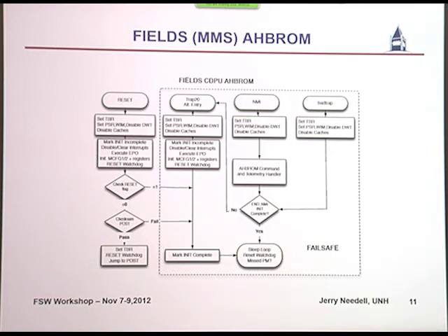In this case, the only telemetry required and the only telemetry produced by this is either response to a command, and that response to a command, as you'll see later, is only going to be a read of a memory location, and then also a heartbeat status whenever probed by the higher level instrument, the higher level processor, because if we don't respond with that, it'll turn us off.